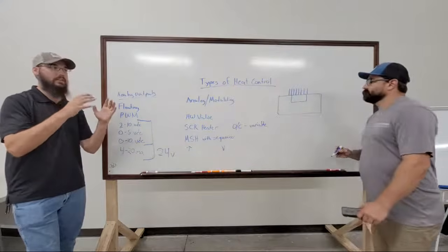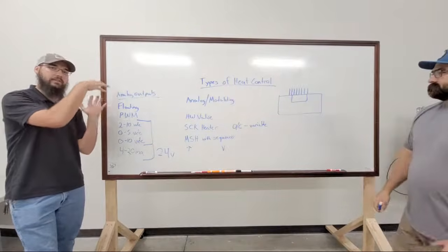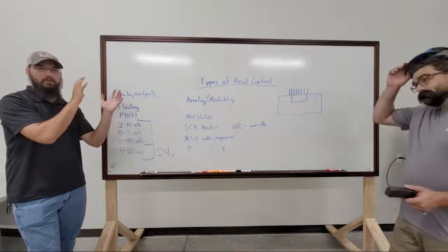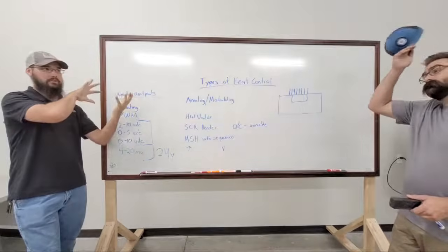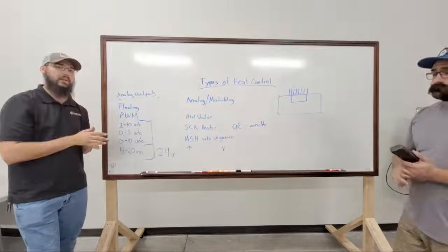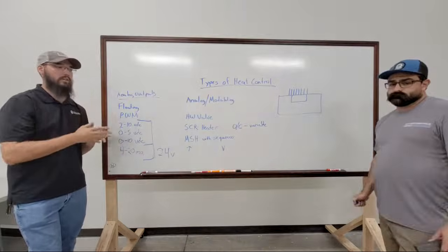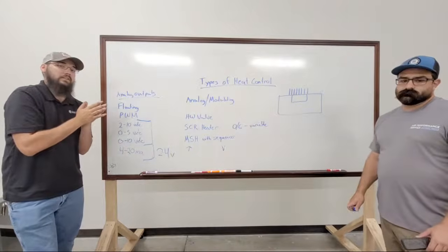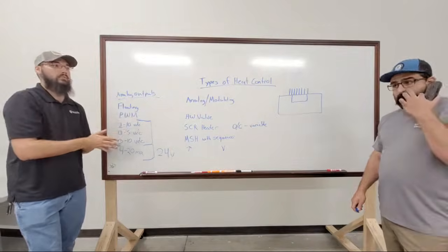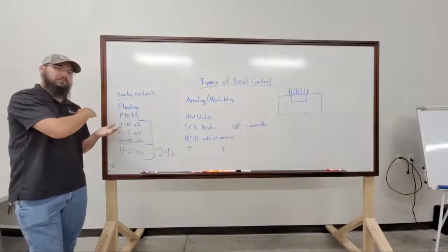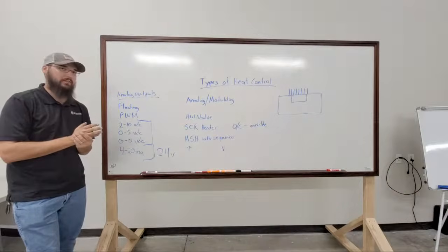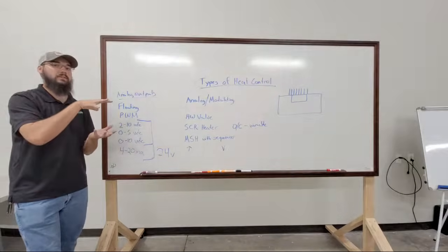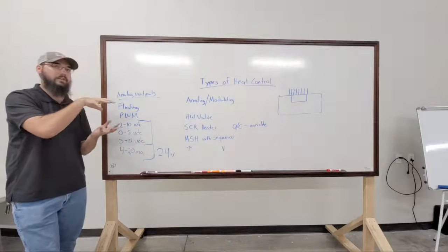But they'll have a large heat sink just hanging out the outside of the control cabinet, and so if you walk up to a terminal unit and you see this weird looking strange aluminum device just hanging off the side of the control panel, you are almost guaranteed you've got some SCR type device, and that is a heater to reject heat. So if you ever have a building that gets re-insulated for any reason, they have to be careful not to coat that heat sink because it will cause that module to overheat and fail.